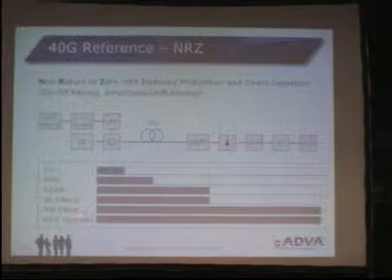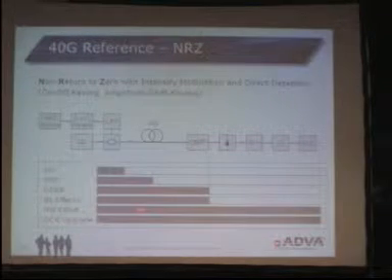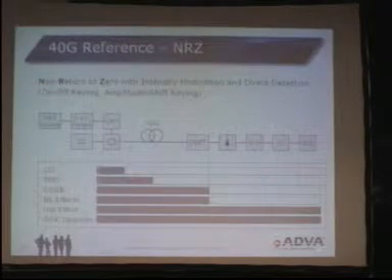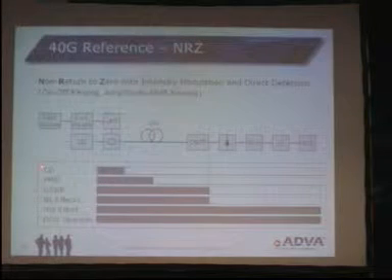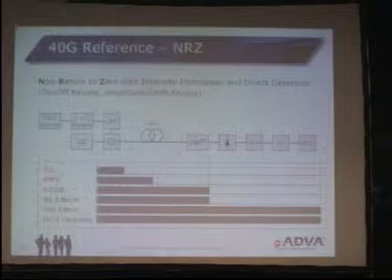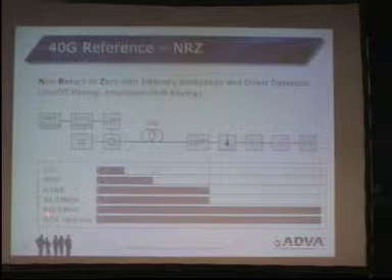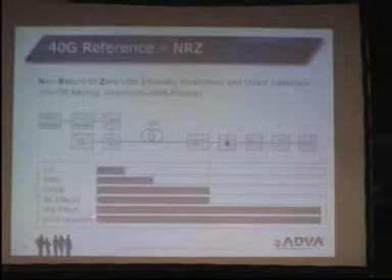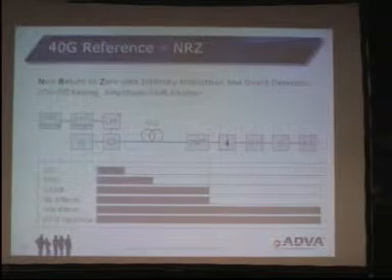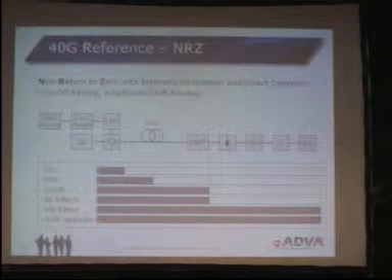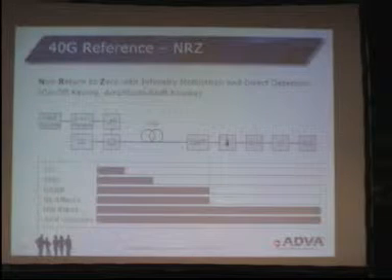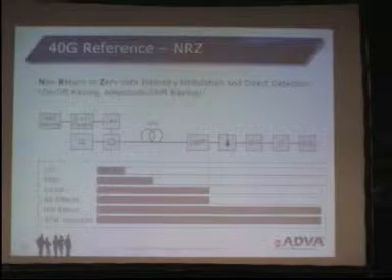I try to characterize this. The longer these gray bars are, the better it is. So relatively poor behavior with regard to chromatic dispersion, relatively poor behavior with regard to PMD. But for example, low hardware effort, which is good, long gray bar, and obviously, since it is exactly the same technology, it can be used for upgrades of 10 gig on-off keyed systems. This is relevant. If this isn't there, I can't use the technology for upgrading existing 10 gig systems.